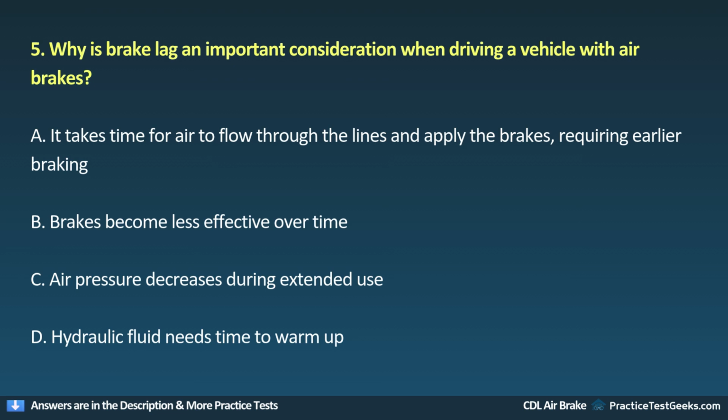5. Why is brake lag an important consideration when driving a vehicle with air brakes? A. It takes time for air to flow through the lines and apply the brakes, requiring earlier braking. B. Brakes become less effective over time. C. Air pressure decreases during extended use. D. Hydraulic fluid needs time to warm up.